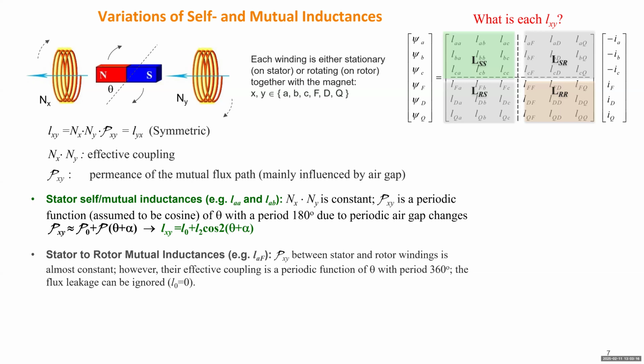And this one is revolving together with the magnetic, okay? So which means the permeance will be basically constant, but this product will be changing periodically. Because right now, the two axes of the two windings are parallel, that is the largest value if we consider this as a dot product. But if they turn by 90 degrees, this one will become 0, right?